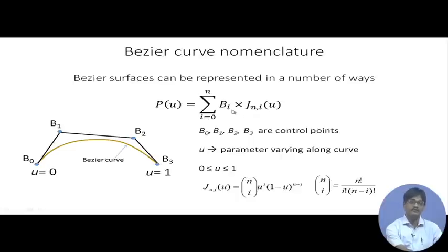So, if the control point coordinates be x, y and z, that means, if it is a 3-dimensional curve, in that case with each of these coordinate values this Bernstein polynomial will be multiplied, and it will be contributing to the x, y or z value of the particular coordinate point being calculated this way on the curve.